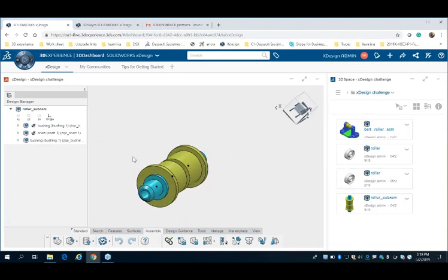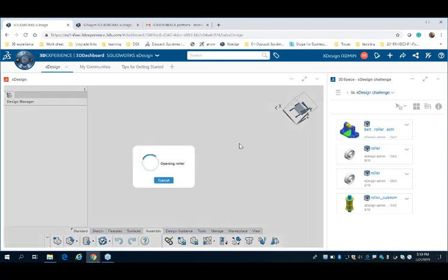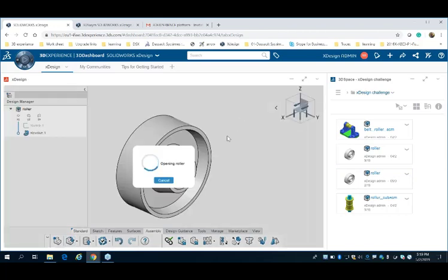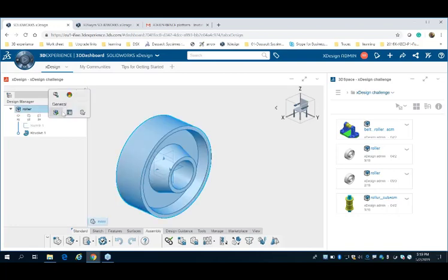Remember one thing, when you are working on a component and your work has started, just go to this bottom side and close your component. Because if you have a roller opened, for other users it will show that it is opened by Prashant and you don't have access to it. It will show you a restriction window over here. Just click on the roller name. It will give you a pop-up. In that pop-up, you will have a not reserved and reserved by you option. It means this component is opened on my side and it is reserved by me.